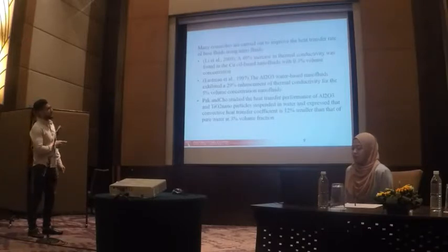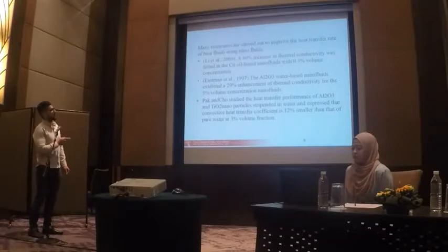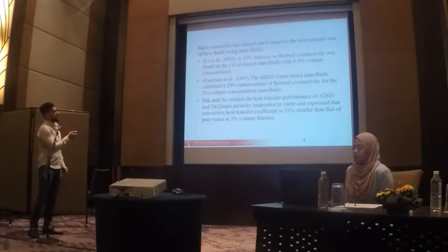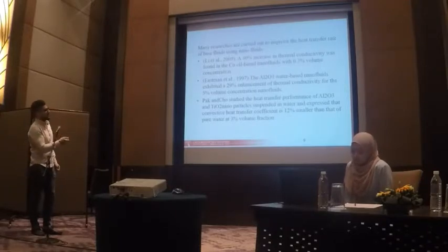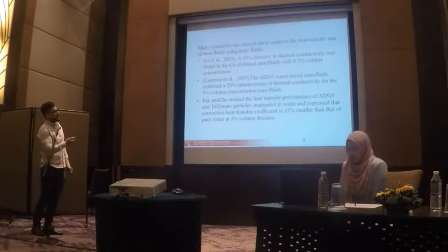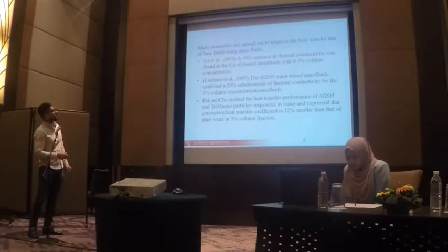Another study using Al2O3 with water-based nanofluid had 29% enhancement of thermal conductivity for 5% volume concentration. And another study using TiO2 found the heat transfer coefficient is 12% smaller than that of pure water at 3% volume fraction.